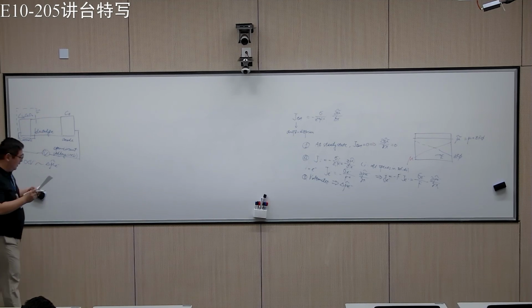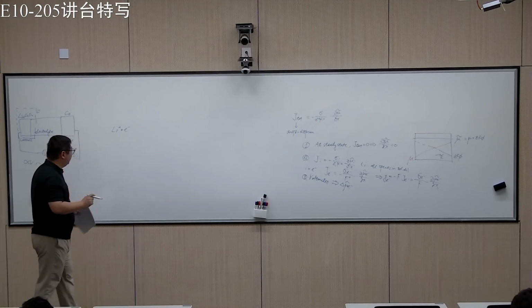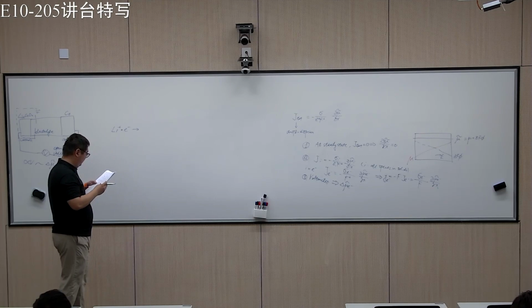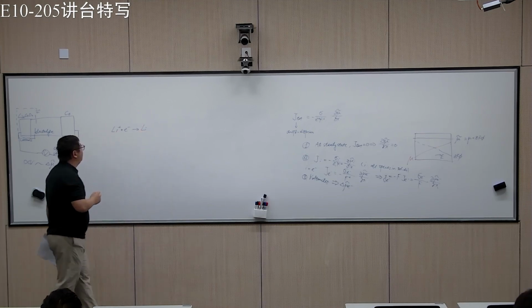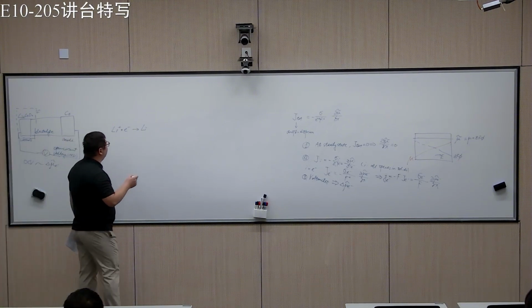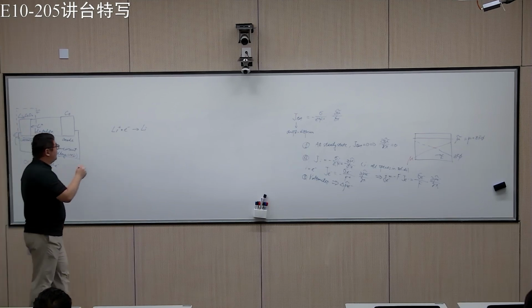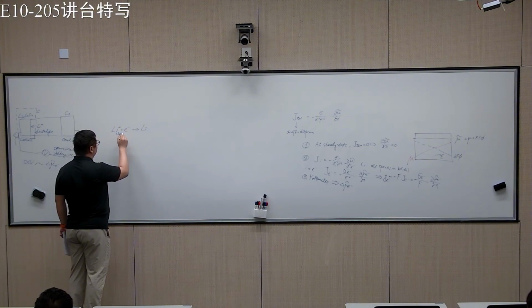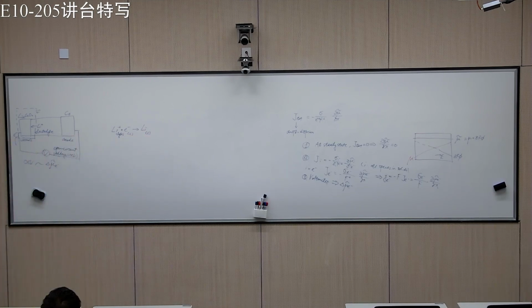We know the reaction for the cathode, let's say if we are discharging the battery to produce electricity, we have lithium from the electrolyte coming from here, and the electron coming from here, going into the lithium cobalt oxide. So this is from the electrolyte, and this is coming from the cathode, going to charge-neutral lithium in the cathode.